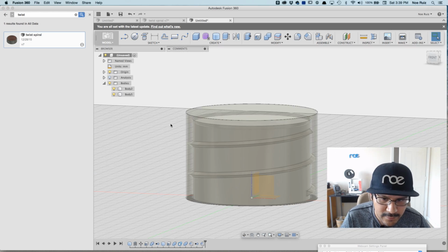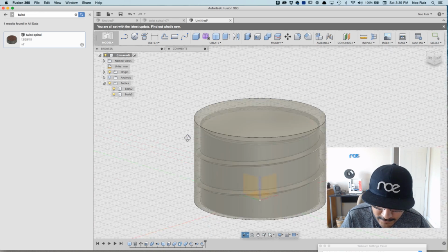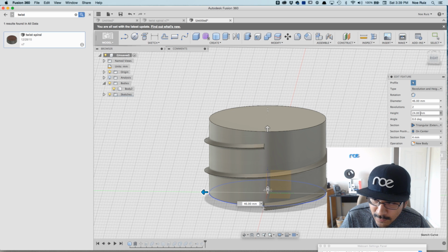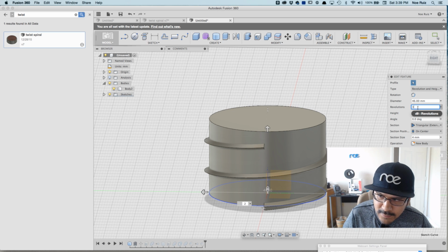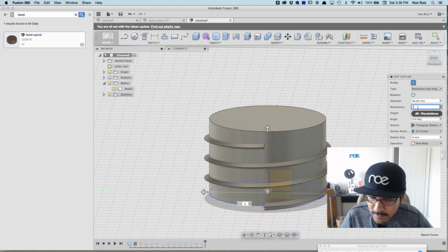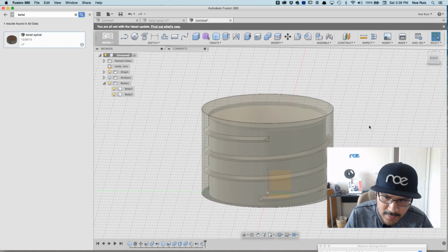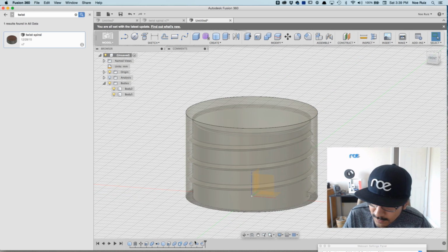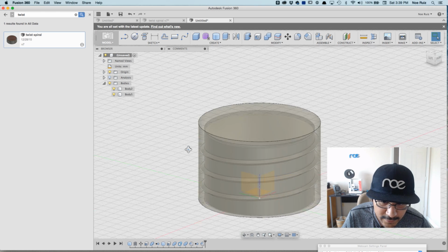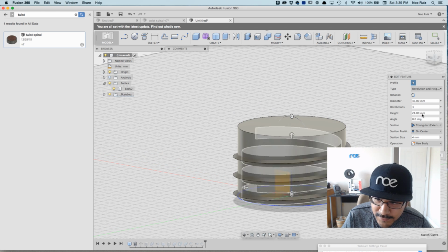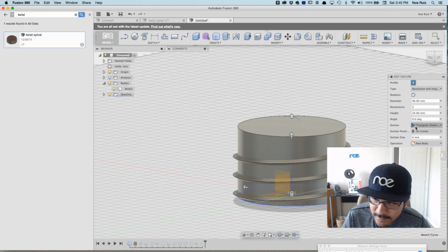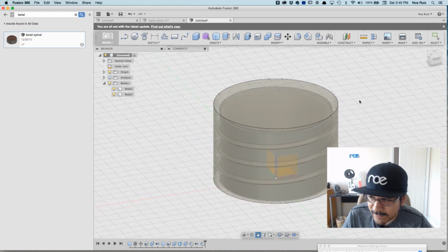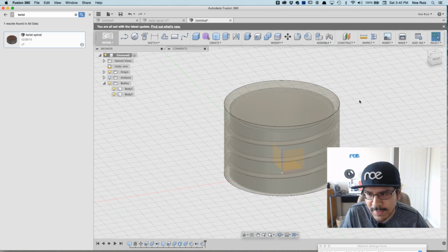So one cool thing about it is it's very adjustable. It's very flexible, right? So if I go back here to the coil, let's say I want to add 3 revolutions. So I have to kind of add more rotations to it. So I'll hit OK, and then everything just follows through that. So again, parametric timeline is super amazing, and it's very flexible in that sense. And you could probably modify other features, like maybe the thickness or the section size of it. But I found that 4 millimeters works pretty well. And printing at about 150 microns is a little bit better too.